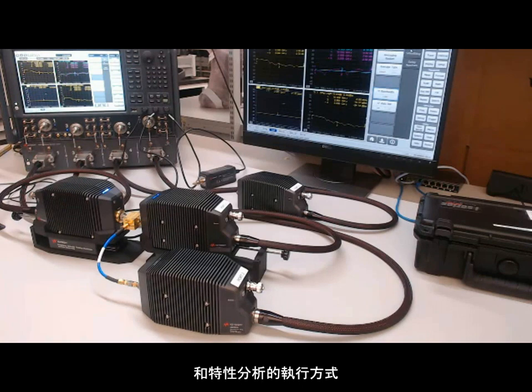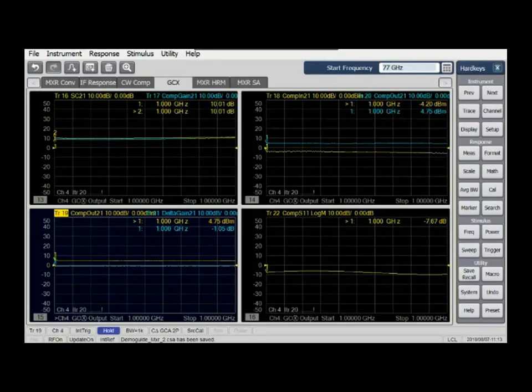Next I'll go through how each of the measurements and characterization of this mixer can be done. Hello and welcome back to the demonstration for the mixer measurements. What we're looking at now is the actual instrument display, and we're going to do a few measurements on this mixer. We're going to look at its conversion, its IF response. We look at it from a CW perspective in terms of compression, and then over frequency, and look at harmonics and mixer output using a spectrum analysis method.